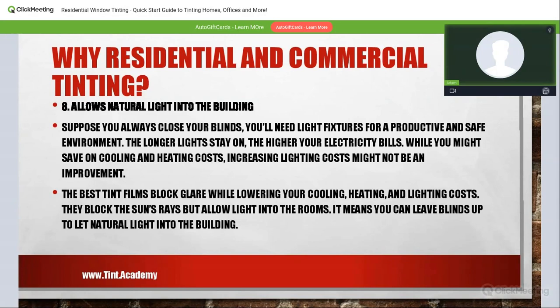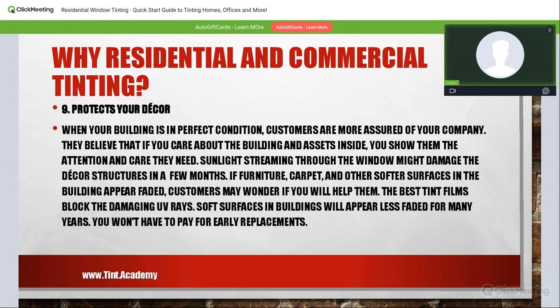We did a 35% VLT mirror film because the customers, when they're sitting in the lounge part, if you've ever been to the Keg for a meal, they have that really cool lounge. It actually affected the customers where they were very uncomfortable, but they still wanted that natural light. So we used a 35% VLT, visual light transmission, with the mirror look. It blocked out the UV but still allowed natural sunlight, which wasn't affecting the customers.